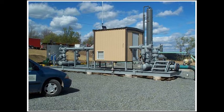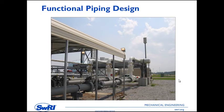And here's one step that approaches that. They attempted to do the same thing by putting their valves in this position. I guess they were able to get about 5 diameters of straight run entry from the header into the meter run. However, it would have still been better had they shortened the skid, dropped the header below ground, and then tied in the riser straight down into that header.